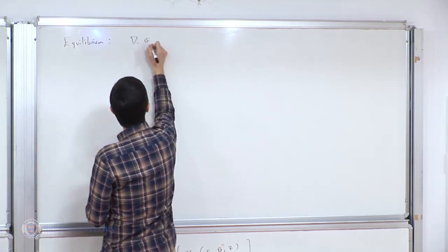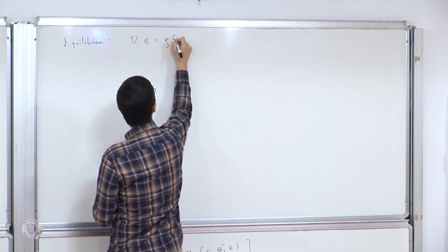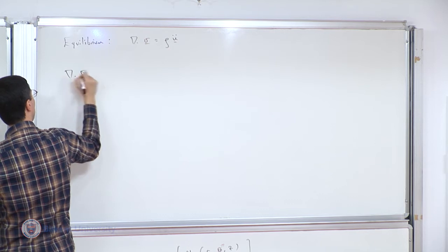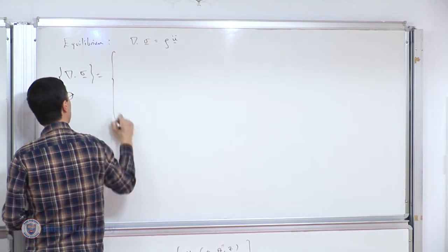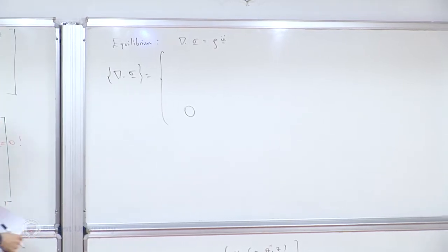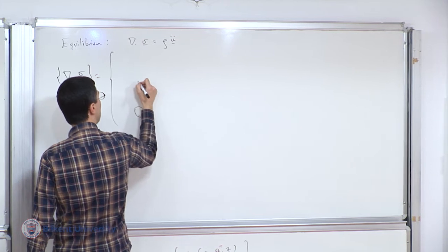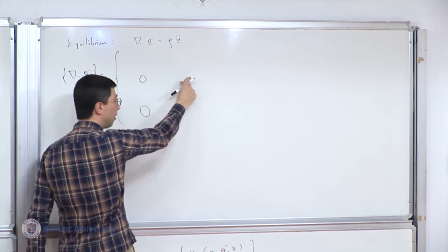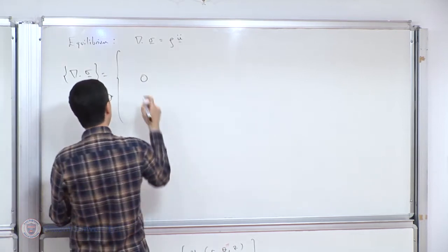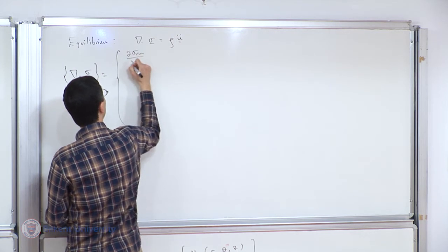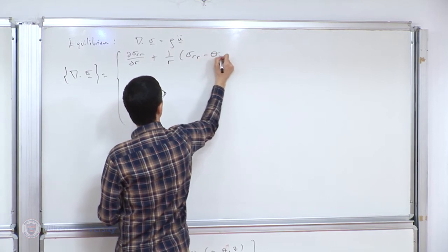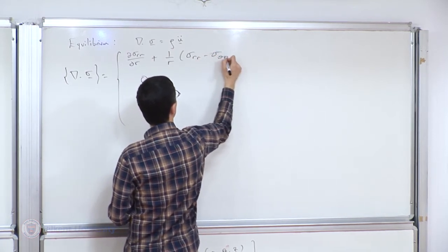So we have divergence of sigma is rho u double dot, and let's go ahead and write that with what we have. In our setting, because there is a plane stress situation and there is no angular dependence of any component, the theta component and the z component of the divergence vector are 0 from the outset. We can omit them, and what only remains is the radial component. We have written that several times before. It looks like this.